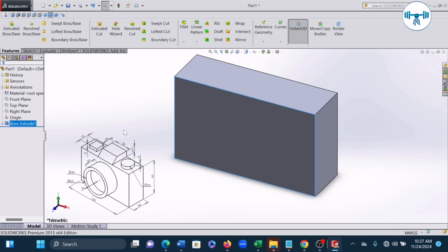Okay, next step. Now what do I do next? Now I would want to draw the 2 circles on our front plane, representing the lens of the camera. You can see it, the lens of the camera. So I want to do that. Let's look at the circle. There are 2 circles of 50 mm diameter and 30 mm diameter, the inner one. So we are going to draw the outer one, then we are going to drill the hole. So we are going to draw the outer circle, which is the diameter 50 circle, and then we are going to extrude it by a height of 20.